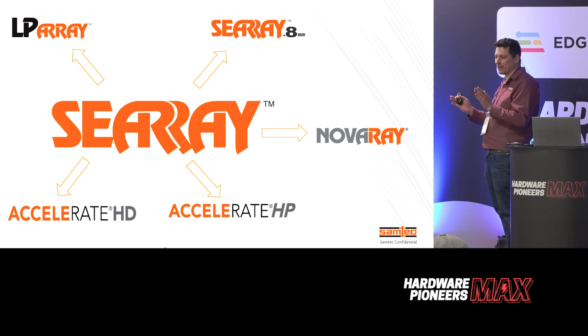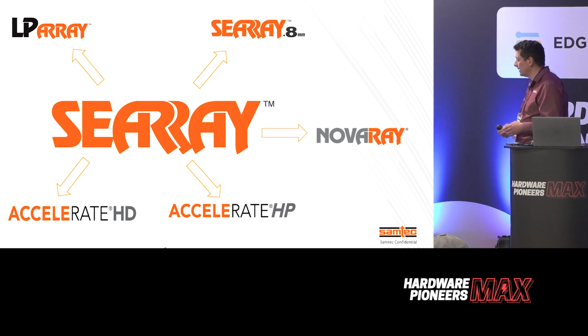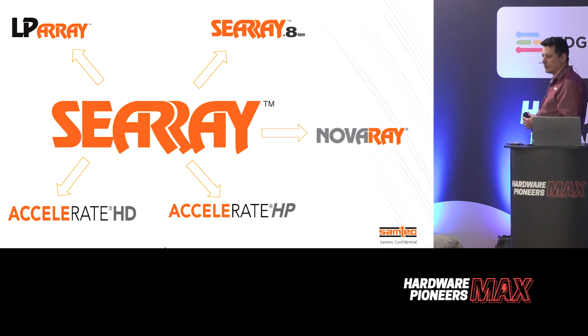So what we do is we space out the columns, the rows, into 2.2 millimeters, so it reduces a lot the crosstalk between the columns, and it allows us to get into higher speed performances.